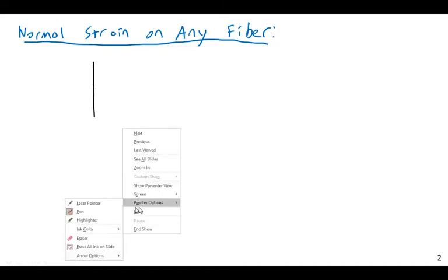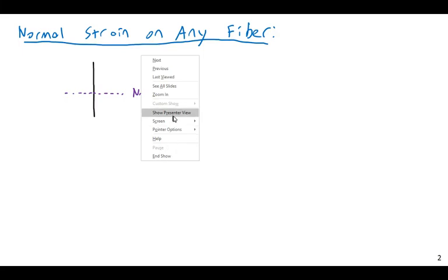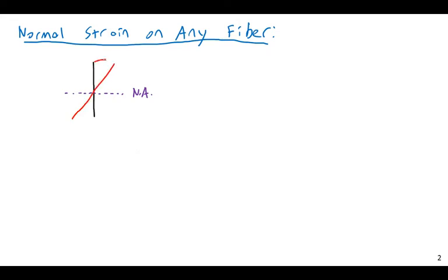So I'm just going to make my familiar strain diagram for a linearly elastic material under elastic bending. You've seen this a million times by now, you're probably getting sick of it, but it's good to remind us what this is. Up here I'm going to have negative strain at the upper zone because it's going to be in compression. And the lower fibers are going to be in tension. So I'm going to have a strain like this. Here, strain will be positive.